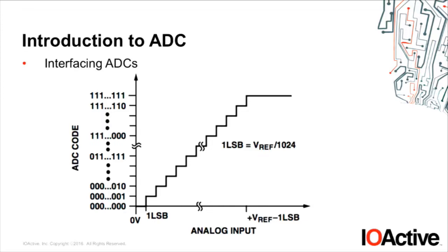Let's say the ADC has a precision of 12 bits, we're going to get 12 bits worth of data. So each bit has a meaning. With this calculation, once we read the whole number, we can do a simple calculation and get the exact value. We will divide that by 1K and we'll get the exact value that we are actually reading. So this is more or less how the ADC works, and how, from the programming point of view, someone would implement a system or a PLC that has an ADC for reading signals.